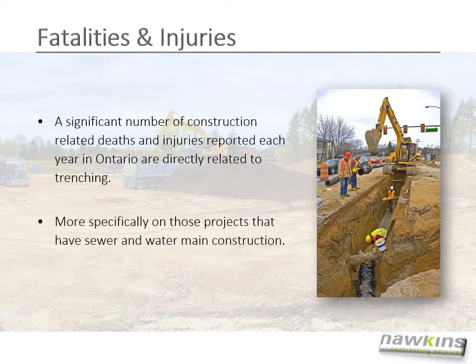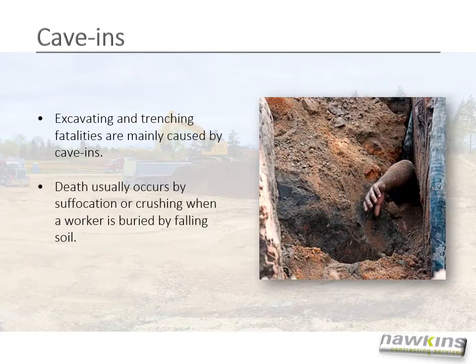A significant number of construction-related deaths and injuries reported each year in Ontario are directly related to trenching, most specifically those projects that have sewer and water main construction. Excavating and trenching fatalities are mainly caused by cave-ins. Death usually occurs by suffocation or crushing when a worker is buried by falling soil.